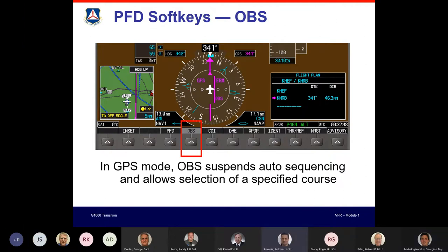So George, if I have an IFR approach, say localizer DME, then I would use the GPS distance. You use whatever the approach asks you to do. So that's going into the IFR part of things, which is not really the focus for tonight. But there's a gotcha.